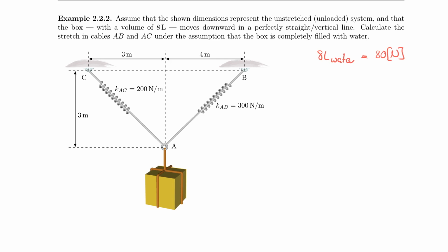The strategy to success is always a free body diagram first, and let's talk about an important aspect of free body diagrams for released systems. So I just released this system here, and what did I do? I really cut through 1, 2, and 3 parts of the structure. But in reality, I only cut through 2 unknowns. So this is not known and this is not known. This is effectively known because I have this value available here to me. Please understand that the only reason I will be able to solve this is because I have only 2 unknowns.